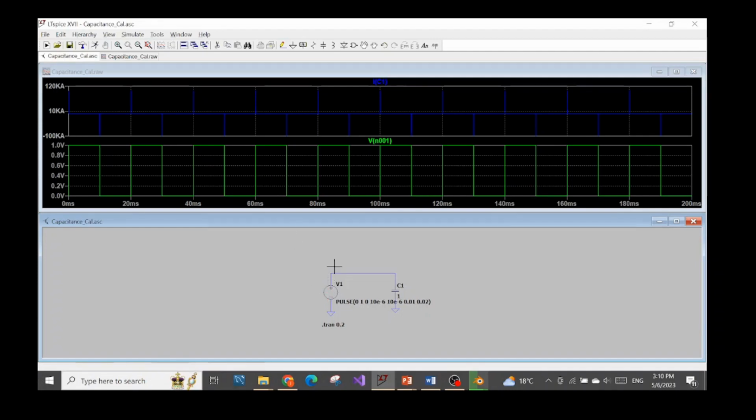So for example, this is your real measurement setup. And then you have a record of your voltage in the time domain, and also the record of your current in the time domain, somehow similar like this, in two files. You can import those two files into your Python code. In the Python code, you can use SciPy, or some built-in library from Python, to apply the FFT algorithm in order to obtain the frequency domain of those two signals.